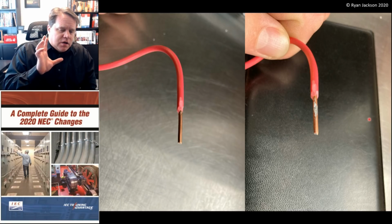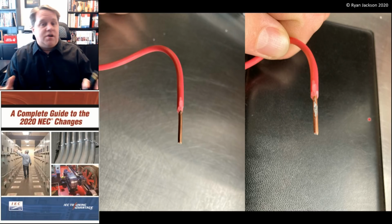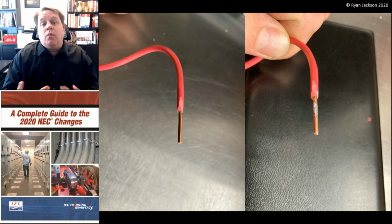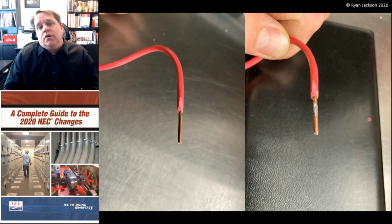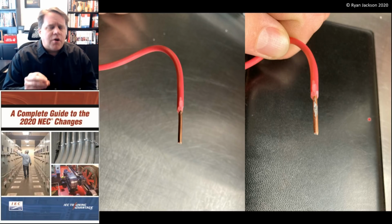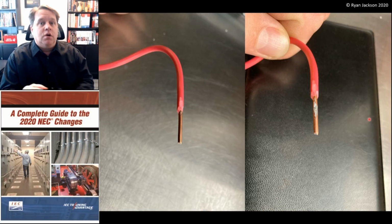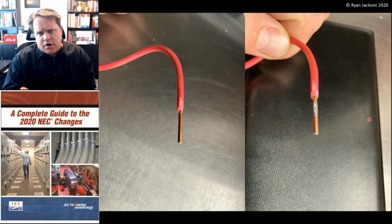Now, if copper-clad aluminum was only around in the early 70s and then it just died off and nobody's seen it ever since, then I wouldn't waste your time talking about it. I think it's interesting personally, but if it's something that you're never going to see, then why would we waste our time? The fact of the matter is, copper-clad aluminum is almost certainly going to be making a comeback. In the 2023 version of the NEC, which we're in the middle of the development process right now, it appears that we're going to allow more uses of copper-clad aluminum. So I wanted to let you guys know what the rules are for copper-clad aluminum.